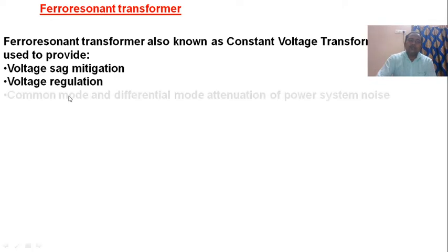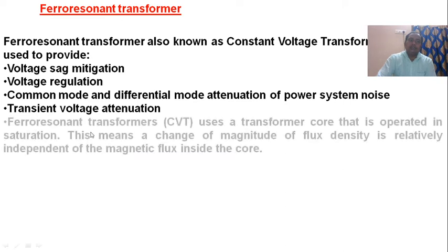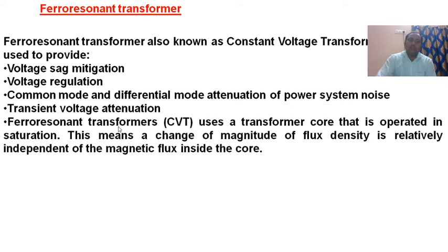regulation, common mode and differential mode attenuation of power system noise, transient voltage attenuation. Ferro-resonant transformer CVT uses a transformer core that is operated in saturation.